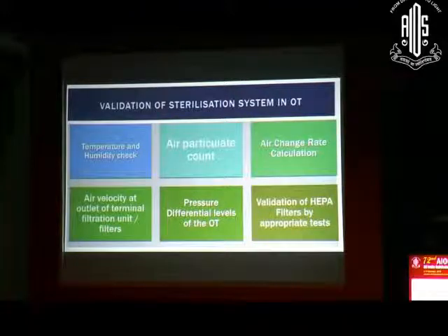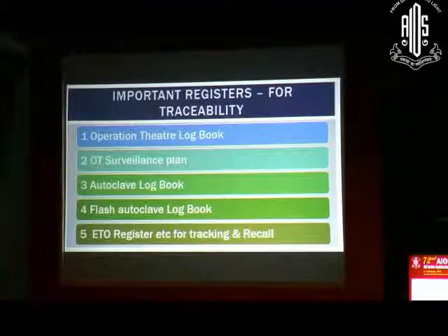So these are the validation of sterilization systems in the OT. I'm sure the next speaker will be covering more on this. The temperature and humidity have to be checked and monitored. The air particulate count has to be checked. The air change rate in a modular theatre has to be calculated with reference to your work as well as the number of surgeries you do. The pressure differential levels of the OT and validation of HEPA filters is mandatory every 6 months or 1 year